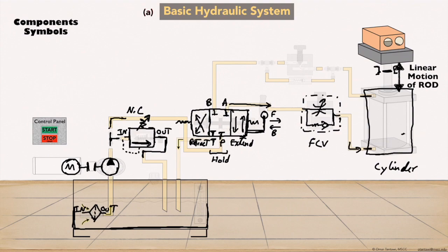So I'm going to draw the piston rod unit. I'm going to start with that piston rod unit. On the rod we have the head unit attached. On the piston we'll draw an arrow like that, indicating that there are 2 cushions for the deceleration unit. One to decelerate the retraction just before it comes to a stop, and one for the extension.